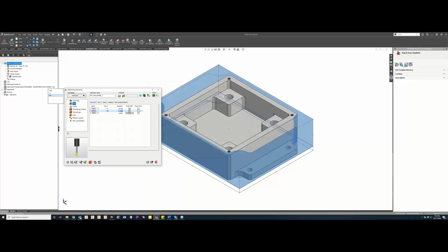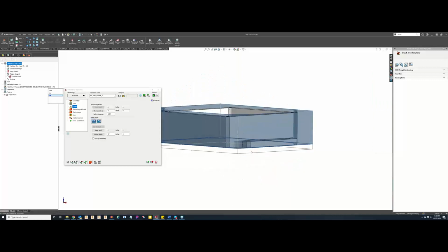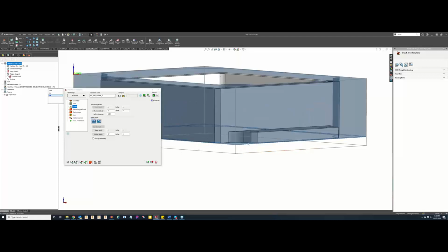You can see this one's sticking outside the holder a little bit farther here, so it's automatically going to compensate for that. Now, I want to go just a little bit farther past. I do have some material, because this is what my stock is currently, this wireframe. So I want to go just a little bit farther past there, so when I flip this part over to do a face mill operation, I won't be running into that sharp burr right there. So I'll just tell it to go -5 mil past.